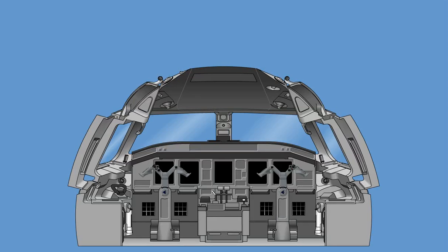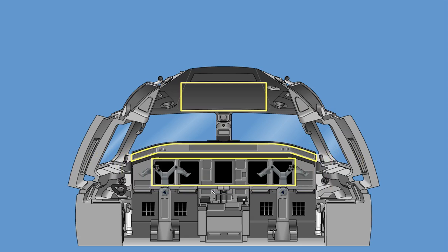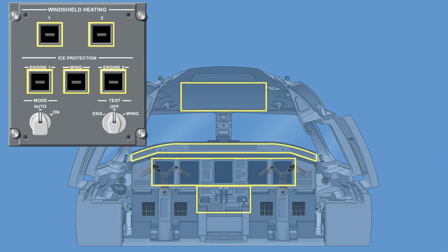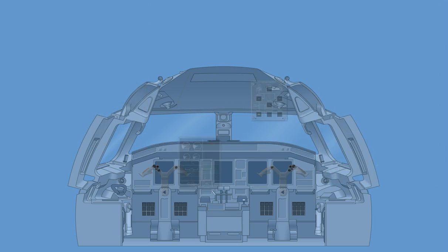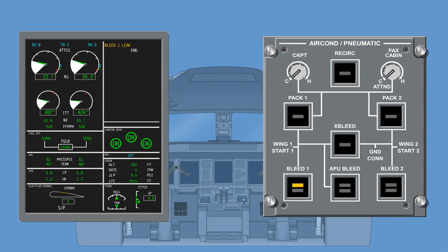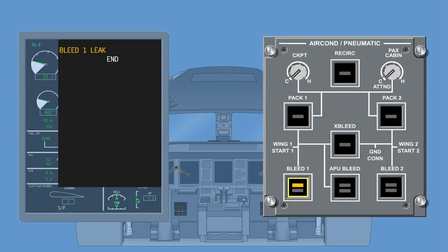The aircraft is designed and operates using the concept that when the engines are started, all systems are normal if the overhead panel, the main panel, the glare shield panel, and control pedestal panels have no striped bar illuminated, no aural warnings are being issued, and the selector knobs are all in the 12 o'clock position. In abnormal situations, the crew will receive visual alert indication that a system is not operating normally.